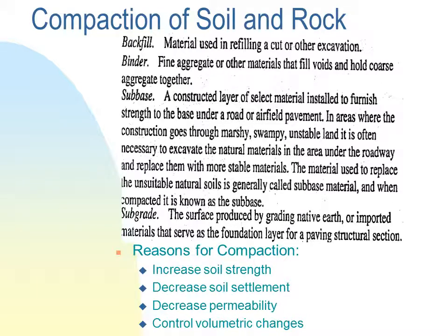We need compaction mainly to increase the soil strength, decrease the soil settlement, decrease the permeability, and control volumetric changes. Most of the failures that you will see in streets in several countries are mainly due to volumetric changes, which is due to bad compaction.